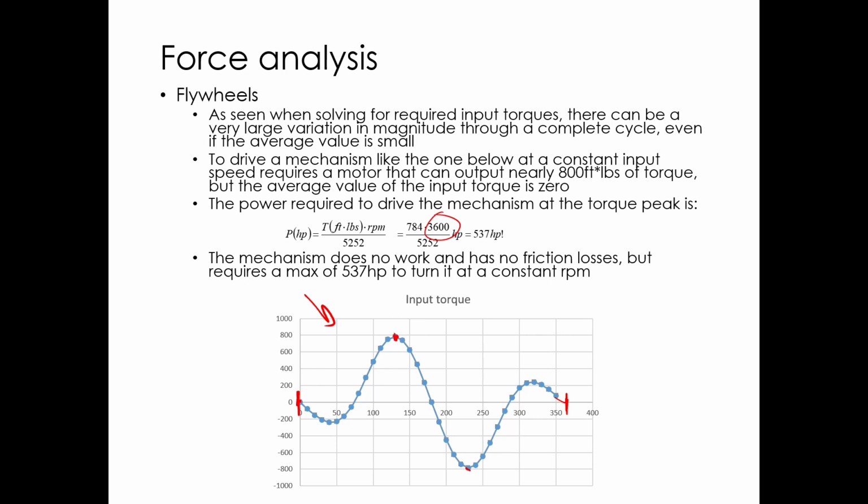So it's this torque demand curve here, since it can't be met in most cases. What ends up happening is the angular velocity of the engine's not constant, and so it'd be continuously speeding up or slowing down through a cycle, assuming no friction losses. If you spin an engine up to some RPM and then you don't have it connected to anything, no friction losses, no pumping losses, anything like that, then you'll see the crankshaft will be speeding up and slowing down continuously.